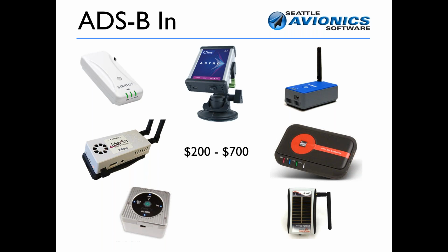The Dynon DRX is less expensive. I don't remember if it's $350 or $325, but it's in that range. The difference between the Dynon and the AstroLink and the Stratus 3 is that while it does include the WAAS GPS and a dual channel ADSB receiver, it does not include an AHRS. That may be one of the ways they kept the price down. So it's quite a bit less expensive.